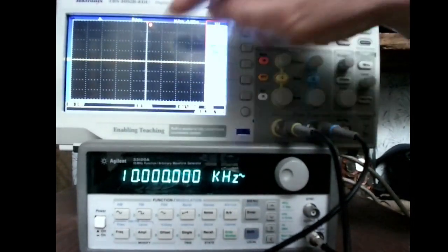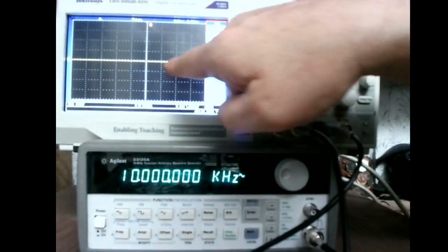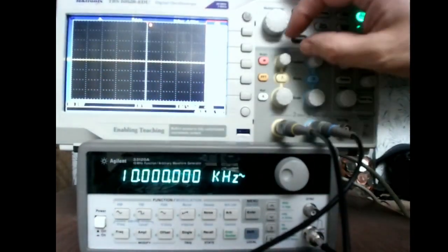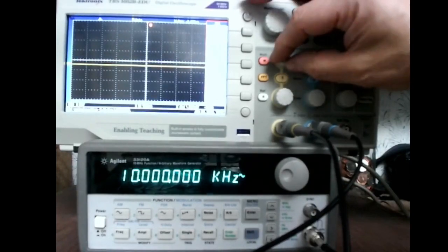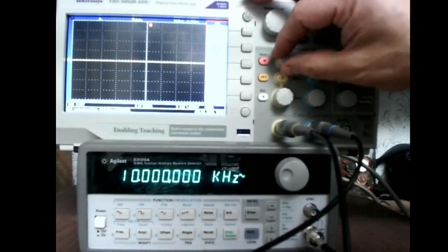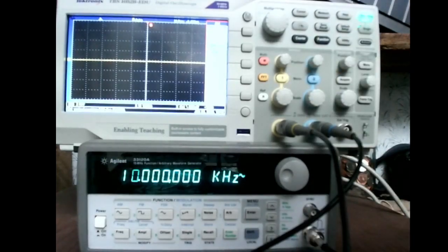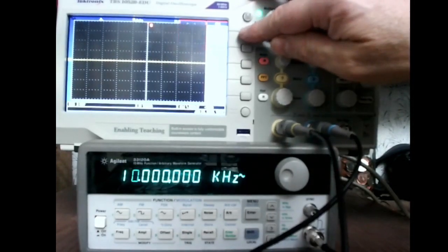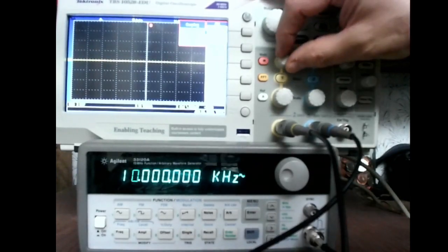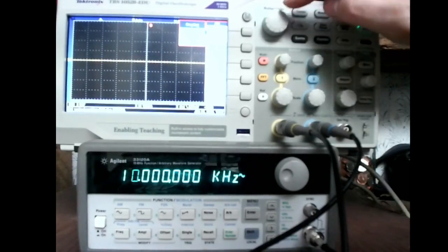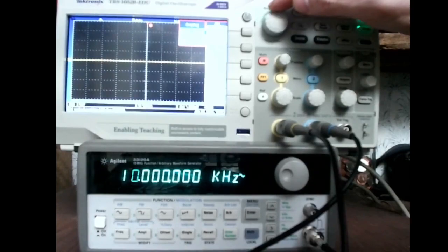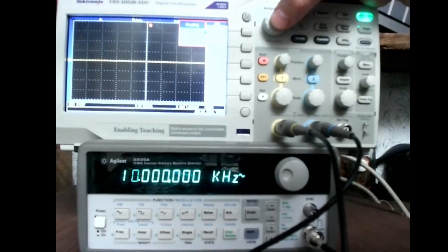So if you just do ground, you see that that just shows you where 0 volts is at. And using this knob here, we can actually raise our ground reference point or lower it. So normally we'll want that right at the center. Sometimes, depending on what you're doing, you might want something else. But we typically want that ground to be right there in the center of the scope. And then normally we'll use AC coupling. And so you use this large knob to select. You can scroll up and down with the large knob and then press the button.